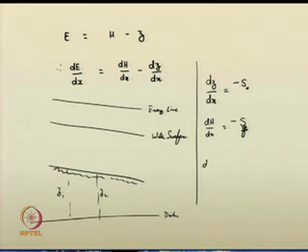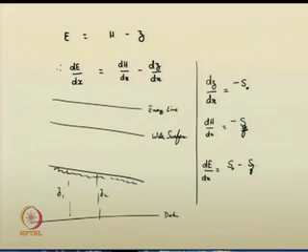Therefore, you get the dE by dx quantity as S0 minus SF. So, why we suggested these things here is that in your dynamic equation, the numerator consists of the S0 minus SF term. So, the numerator term is actually suggesting the slope of the specific energy, right. So, you can think in that direction, we can further evolve these equations, further try to proceed with them.